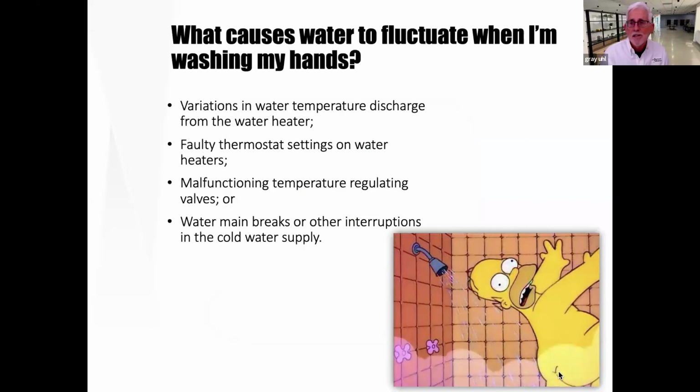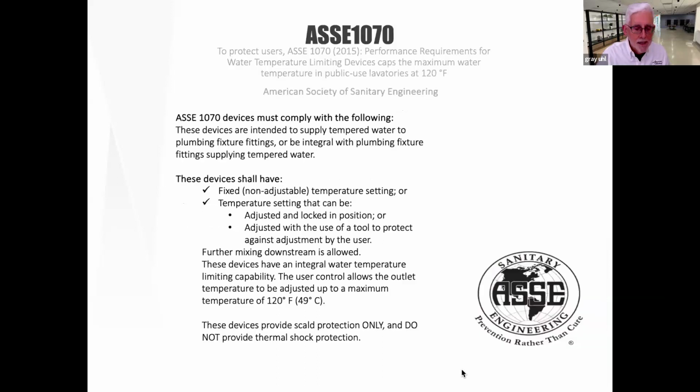Faulty thermostatic settings on the water heater. Malfunctioning of the temperature regulating valves can cause it. And of course, if you have a water main break that disrupts the cold water supply, and boom, you're sent nothing but hot water. All of these can deliver an unfortunate event and cause injury, loss of productivity, and burns to the actual individual worker in the space. So there's a number of different things that can cause it.